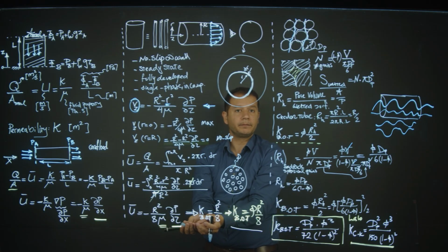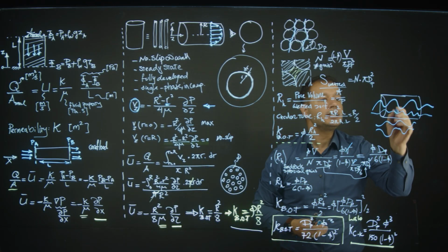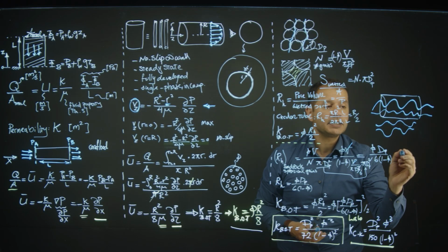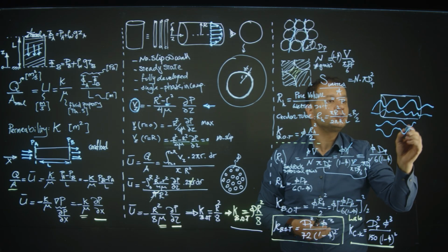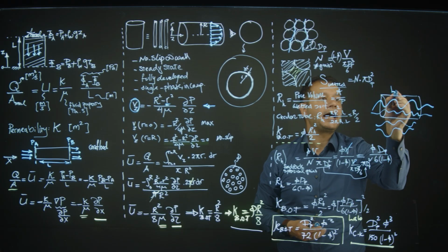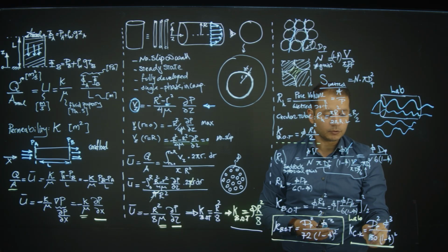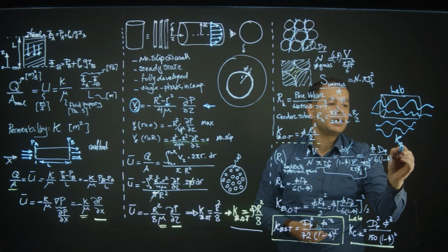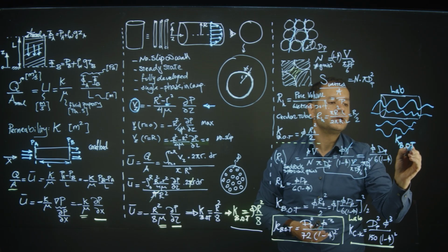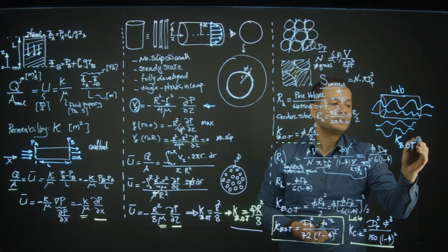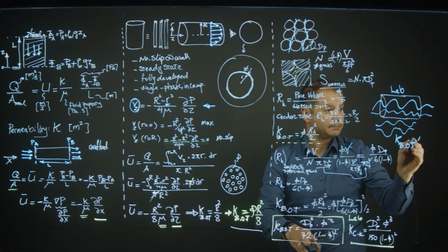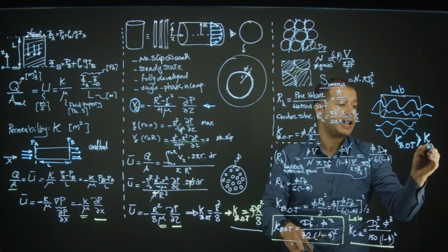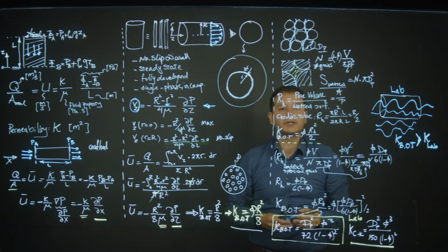of tube theory. This is called tortuosity, and tortuosity is the reason that the real practice permeability in the lab is found smaller than the permeability of bundle of tube theory. It was expected to be bigger than what the permeability from the lab experiment of Karman-Kozeni came.